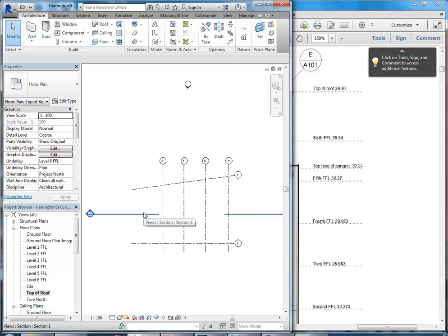If you make the levels go to a certain height, and then come back and make the grids afterwards, it automatically extends those grids through to your highest level. But grids that you make in the beginning, because you won't have those levels, are not as high, and it doesn't extend them automatically. You have to do that manually.